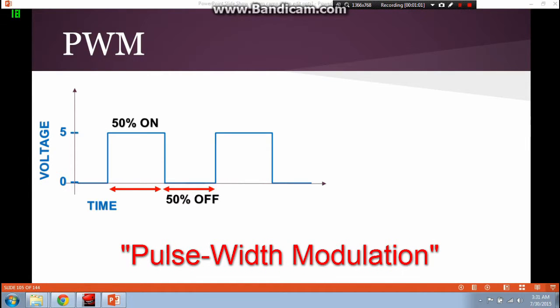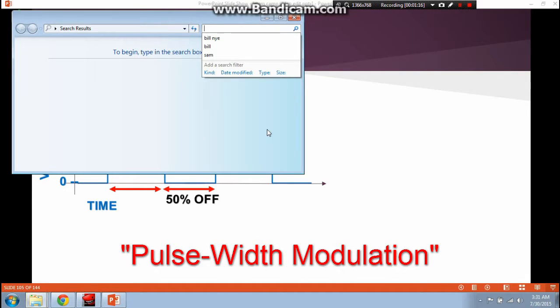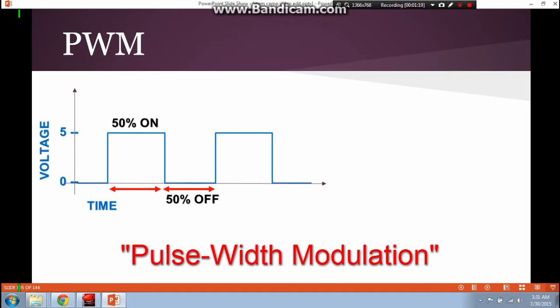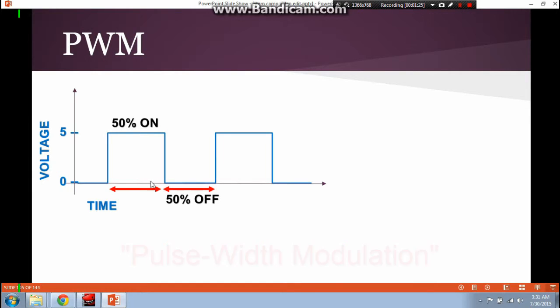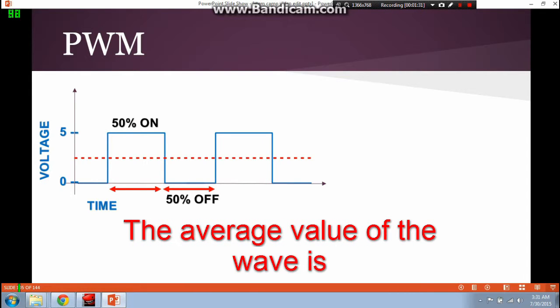It's that by pulsing the width of the signal that we're sending out of our, say we have a pulse signal out of the digital output, just that by pulsing that, we can actually take an average of the pulses over time and cause a new average value to occur from that.